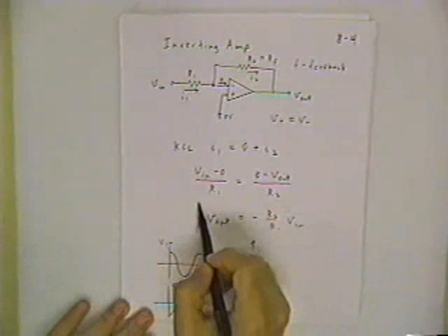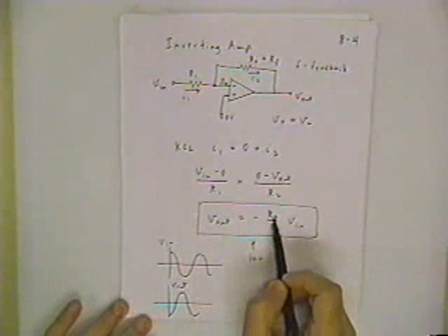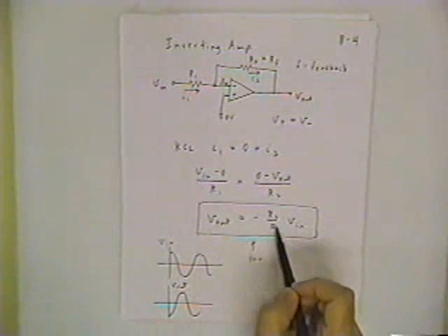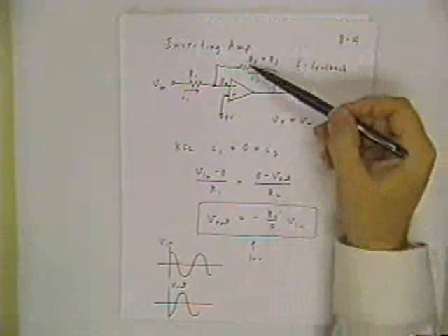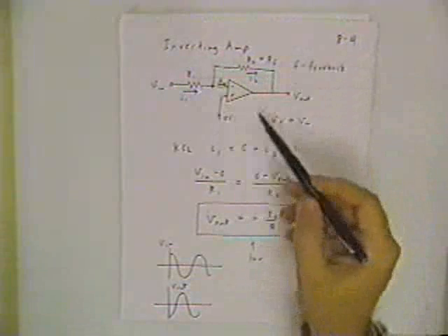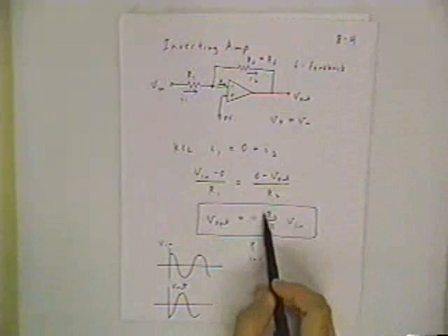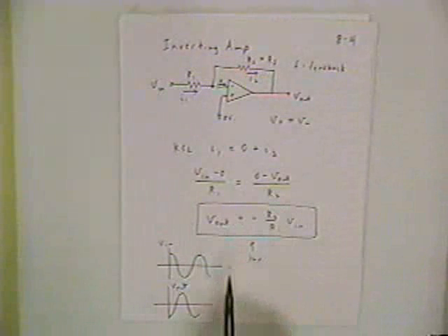That's probably, as I said, the most important thing for you to remember about the op-amp circuit, because what we can also do is substitute impedances for resistances, and we can have RLC combinations here. To figure out the output versus input, you just make these phasors, and make these impedances, and use the same basic layout.